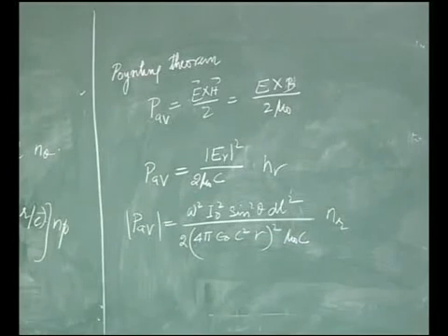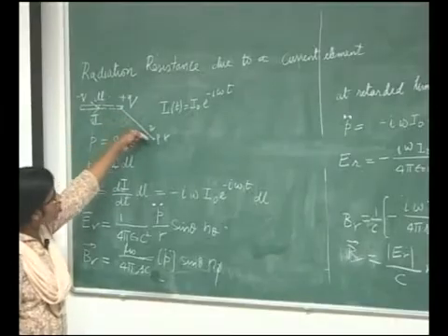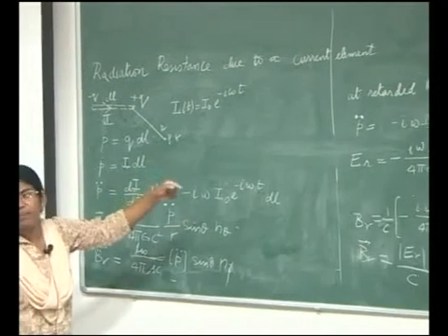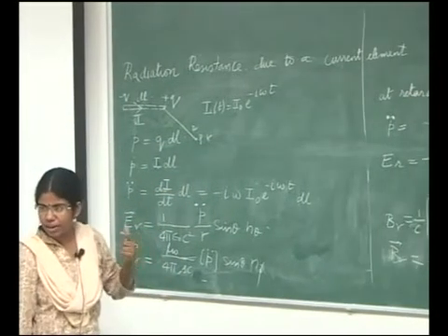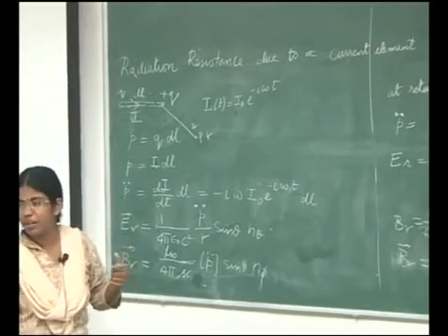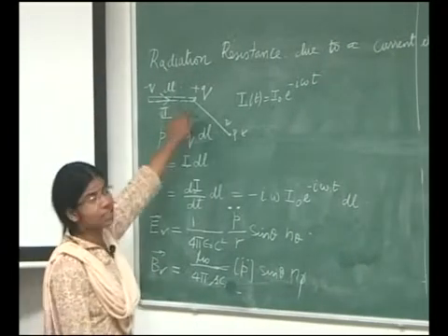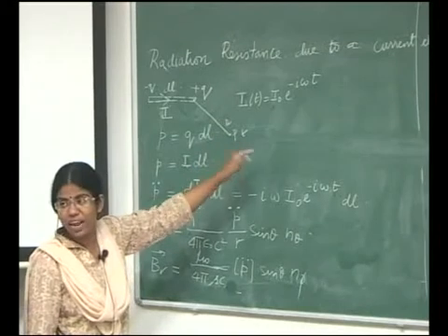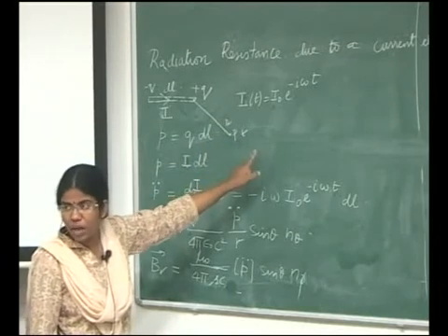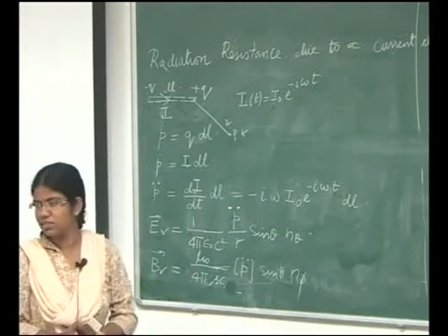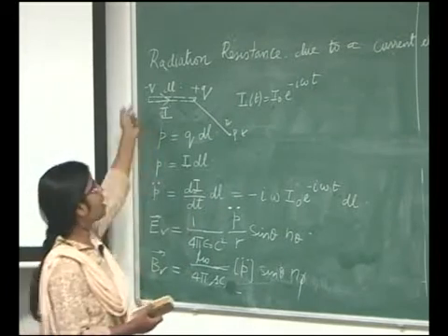Now, we are considering the power radiated along the P direction, but the antenna is going to radiate power in all the directions. A current element is going to radiate power in all the directions. So, in a particular direction I have chosen my point P, but now I need to calculate the total power radiated from the entire surface of this current carrying antenna.